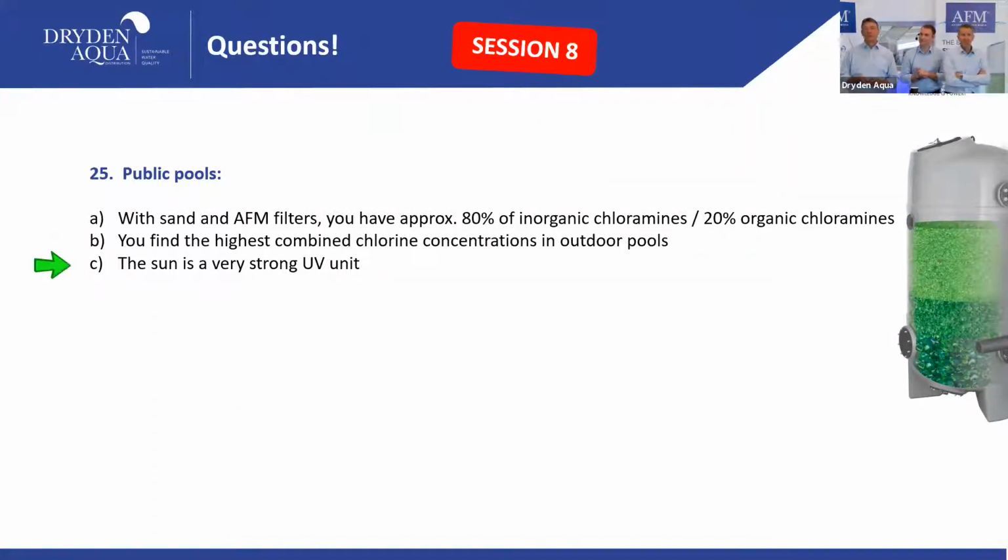That was C. Why? Well, the other ones are wrong. 80% inorganic chloramines is for sand filters, but not true for AFM filters. There it's 80% organic chloramines. And what is the highest combined chlorine? Outdoor pools have the lowest combined chlorine because you have the sun, a big UV system, free of charge.